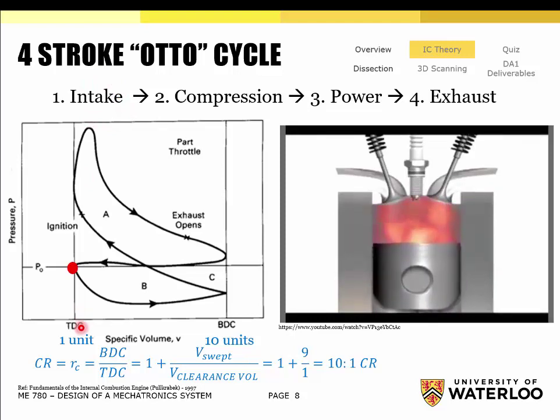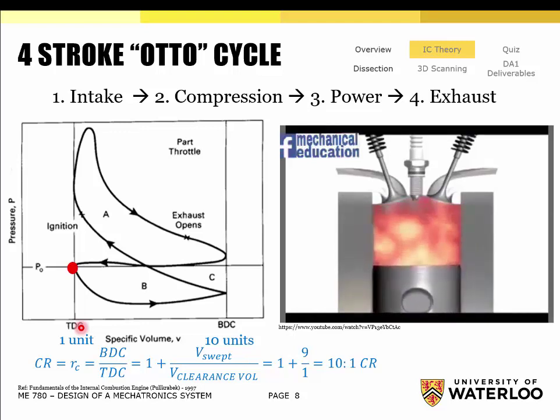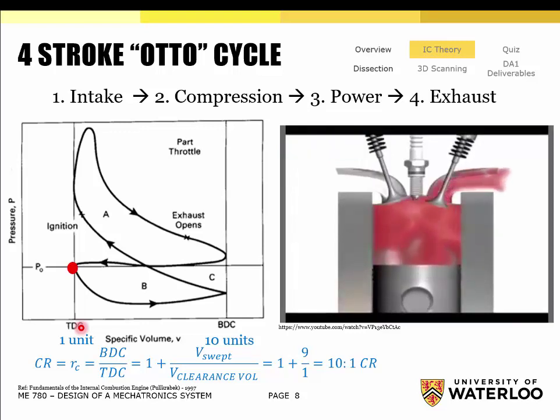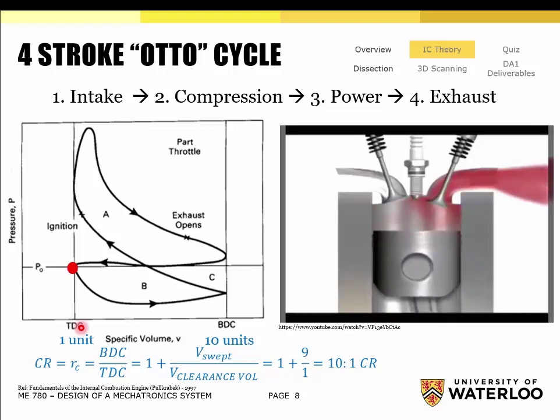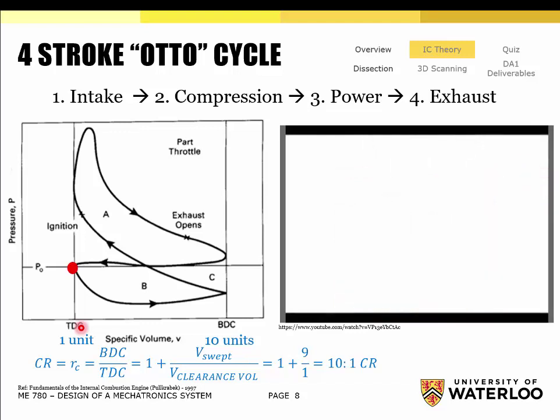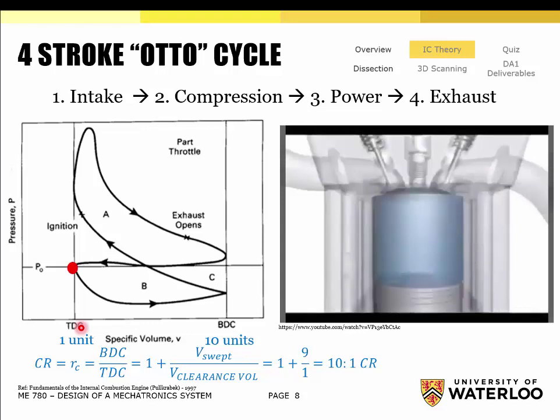Okay, once you expel the exhaust gas, that's what's actually driving that compressor that I mentioned that goes into the intake. Okay, so there's a turbine wheel in the exhaust. Sorry, I don't have a picture to demonstrate to you, but maybe I'll bring one next week that you guys can all look at if you want. And so you have a turbine wheel in the exhaust that effectively increases the back pressure in the exhaust. So all of the pressure in this loop will get larger, and that plays a penalty as well.